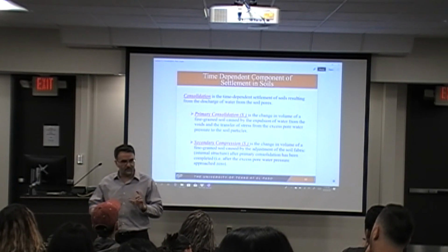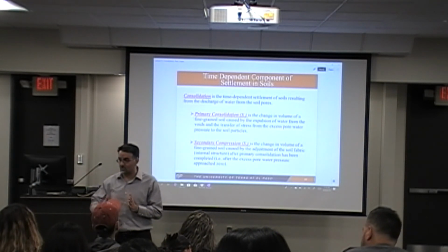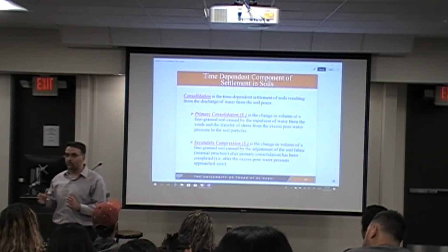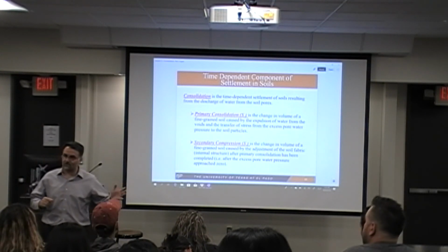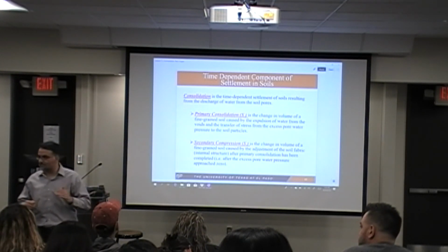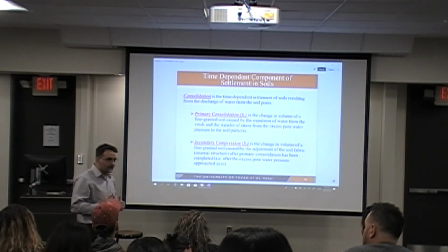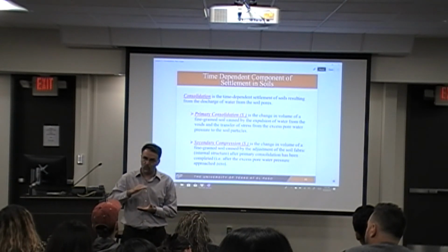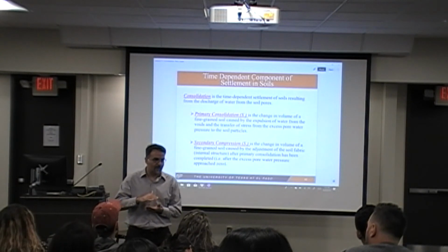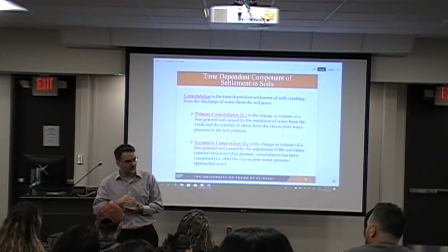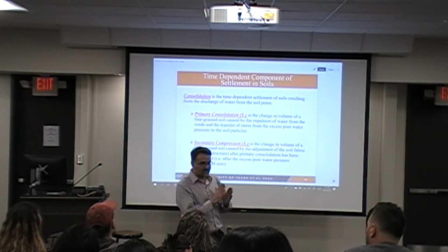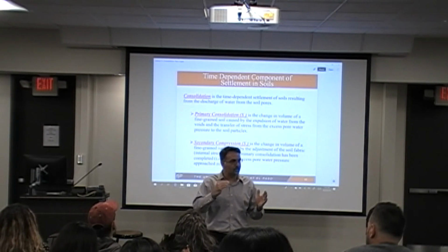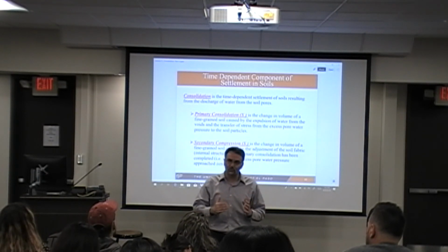So you monitor the deformation associated with the surcharge as a function of time. Next step, day 2, after 24 hours, double the magnitude of load. If you started with 100 kPa of pressure, now the second stage would be 200 kPa. And again, let that surcharge sit there for 24 hours and see what the settlement of the soil would be. Repeat that for 400 kPa. So you do that for 7 points in 7 days, and then you incrementally remove the loads. What happens if you remove the load?